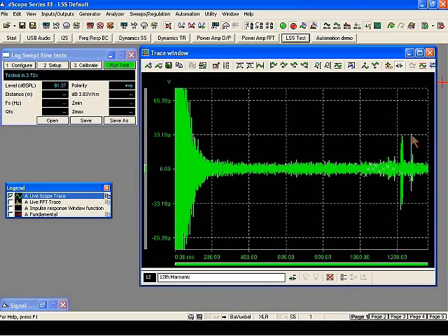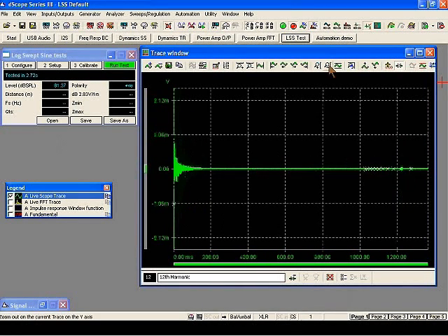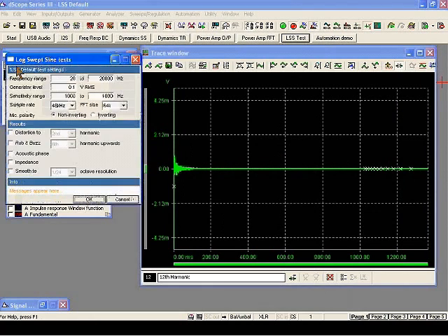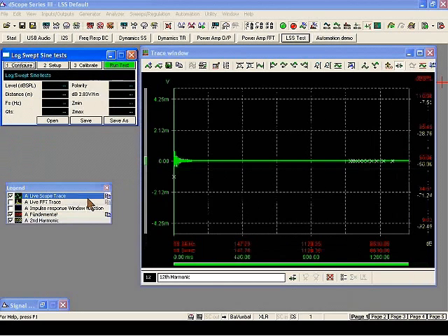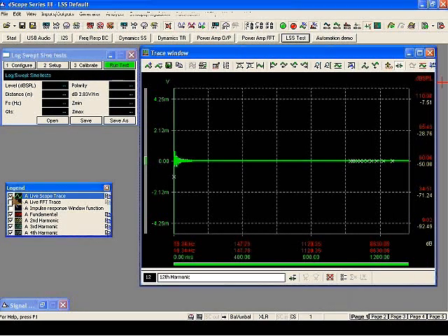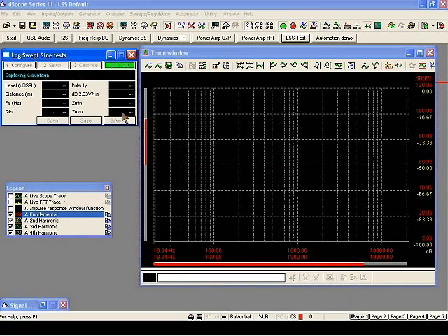So this is the second harmonic, this is the third harmonic, the fourth, the fifth, and so on upwards in frequency. So with appropriate processing tools here, we can actually extract distortion information from the same impulse response that gives us our fundamental frequency response. And to illustrate that, I'm just going to turn on distortion analysis here up to the fourth harmonic in my measurement setup, and I'm then going to repeat the test. So let's hit the button again.